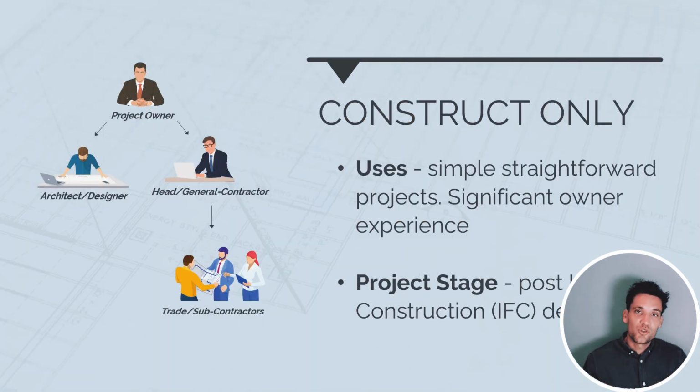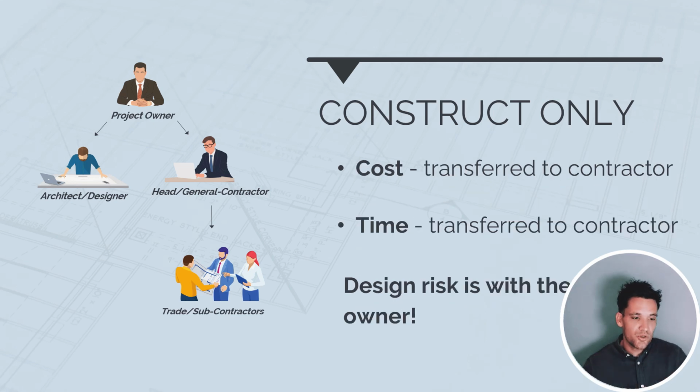Construct-only packages are used for simple, straightforward projects, and they require significant owner expertise. So the owner has to be able to manage the design, capture any value engineering opportunities, prepare a detailed scope of works and package, and then once the design gets to the issue for construction stage, issue this to contractors to quote. So in terms of risk transfer, all the cost and time risk is transferred to the contractor, but importantly, because the owner has completed the design themselves, all of the design risk is with the owner. Any change to the drawings or specifications will be a variation to the contractor.